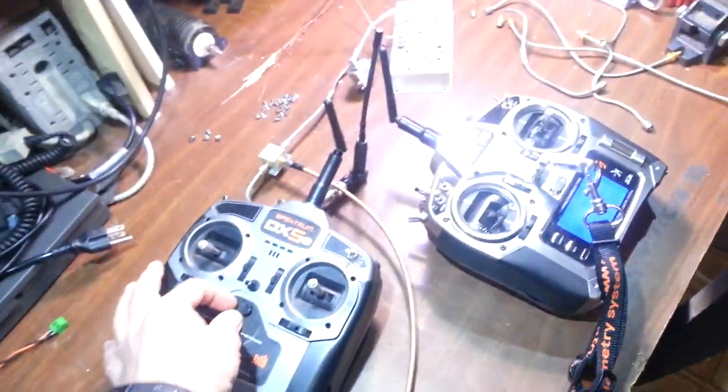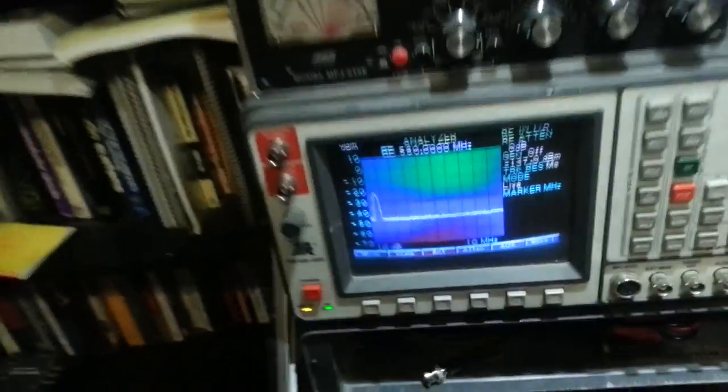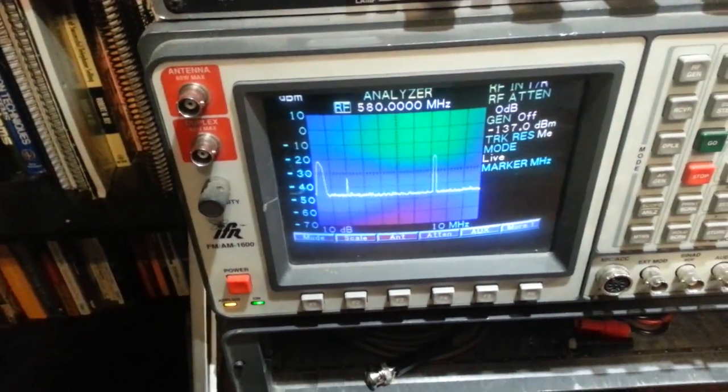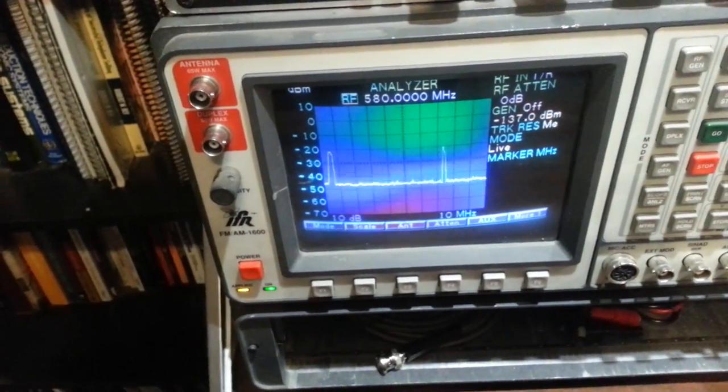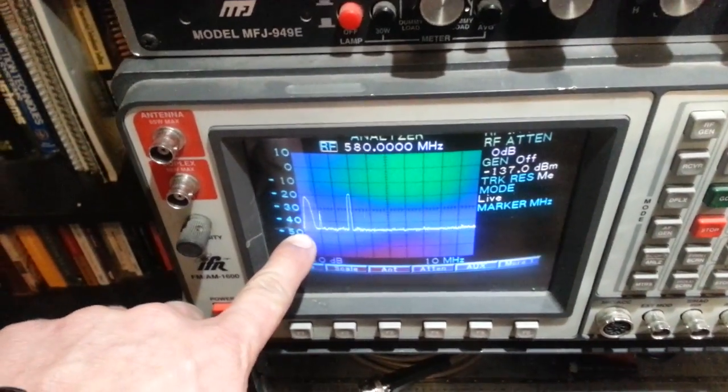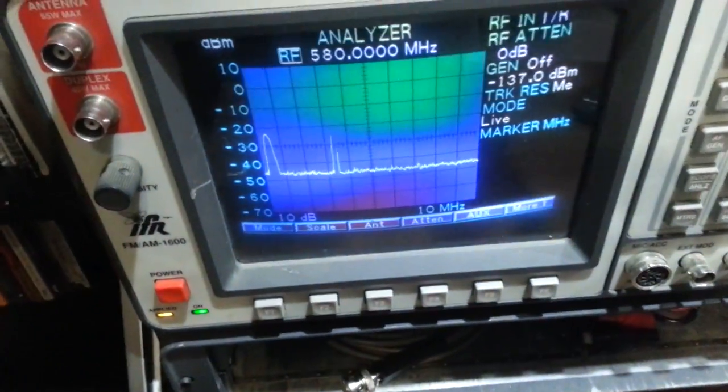Alright, that's pretty awesome. And now let's power both the transmitters on together and see what they do. So you see that, at least the DX7 anyway, avoids the other transmitter. They're not talking to each other, and even though they're pretty close right there, they're still not going to bounce in. And the DX7, because it bounces around so fast, that is called frequency hop spread spectrum. That means it is bouncing around in the frequency, anywhere from 2.4 to 2.5 gigs, always maintaining a signal.